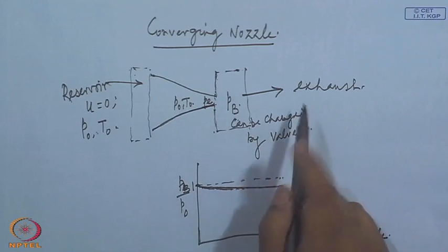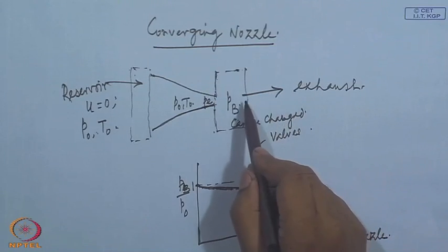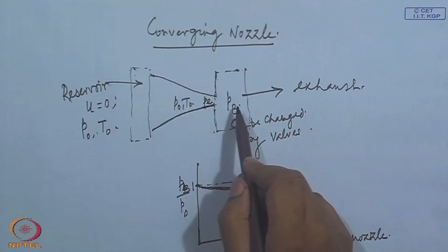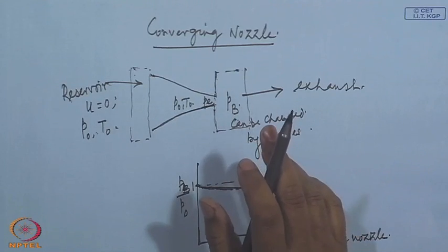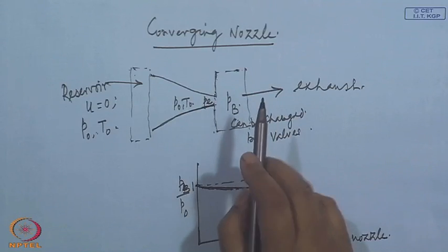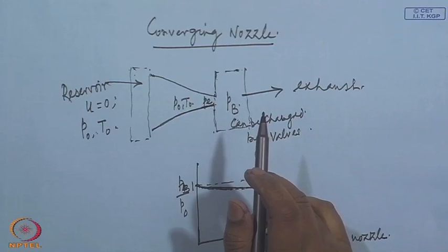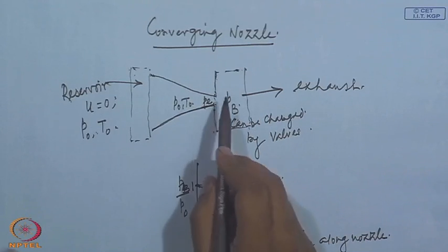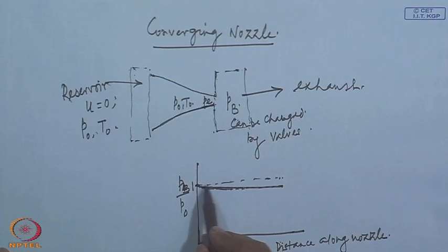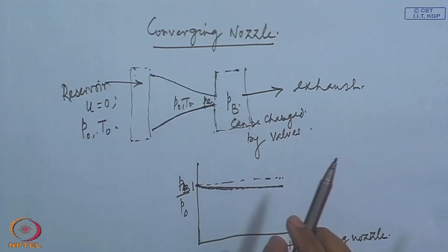Now, since the back pressure is the pressure to which the stream ultimately reaches, P_e cannot be considerably larger than P_b. Similarly, P_e also cannot be substantially less than P_b. So, if P_b is slightly reduced, there is a gentle flow through the nozzle with a continuous decrease in pressure along the duct.